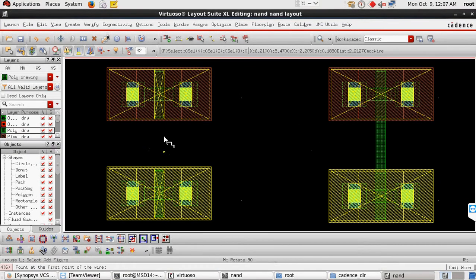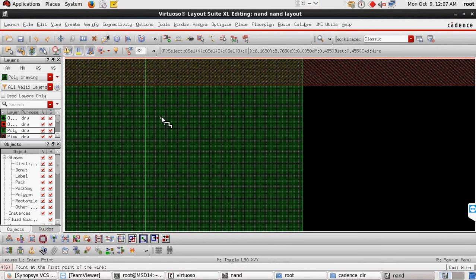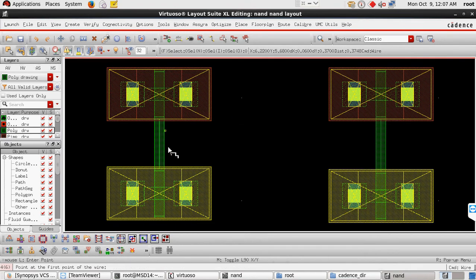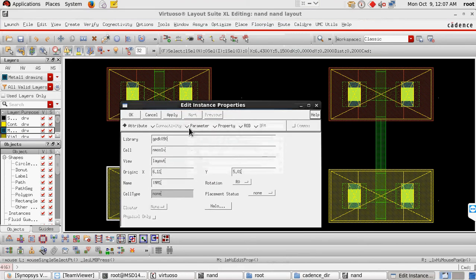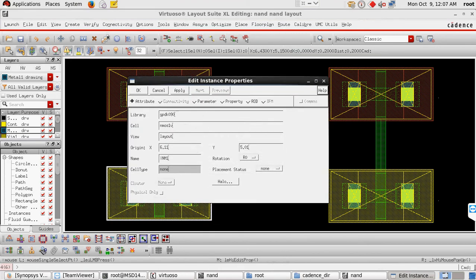Now create wiring. So this makes a direct connection. Okay, no need to move here and there now. This one is also the connection of this part. Okay, before doing it, we attach their bulk here. Actually Cadence provides integrated or detached bulk.